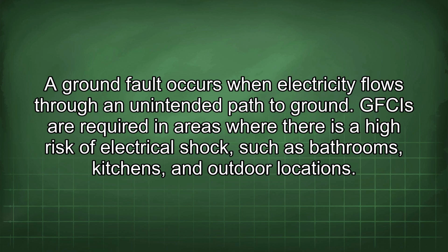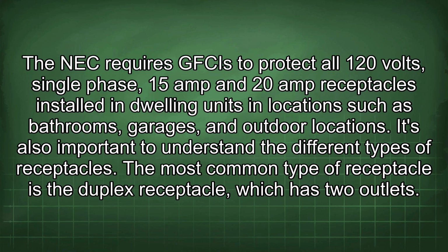GFCIs are required in areas where there is a high risk of electrical shock, such as bathrooms, kitchens, and outdoor locations. The NEC requires GFCIs to protect all 120 volt, single-phase, 15 amp and 20 amp receptacles installed in dwelling units in locations such as bathrooms, garages, and outdoor locations.